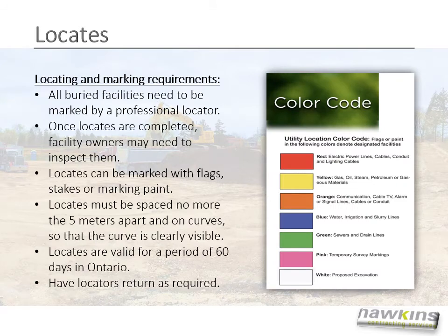There are standards for locates, and that involves these locating and marking requirements. All buried facilities need to be marked by a professional locator. Once locates are completed, facility owners may need to inspect them. Locates can be marked with flags, stakes, or marking paint, but not just any material. Locates must be spaced no more than 5 meters apart and on curves so that the curve is clearly visible. Locates are valid for a period of 60 days in Ontario, and you have to have locators return as required.